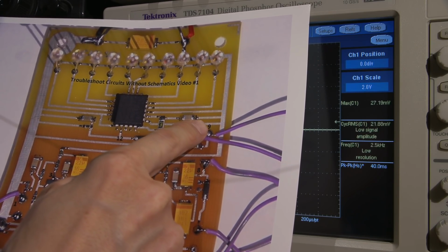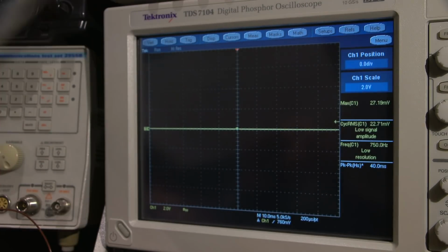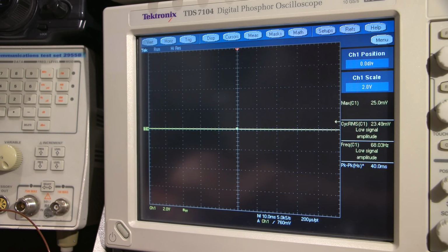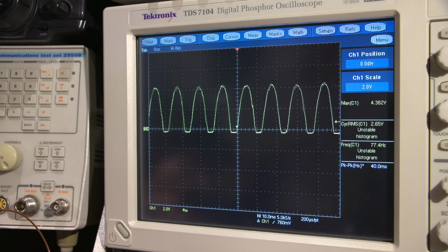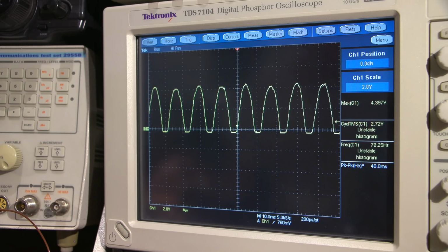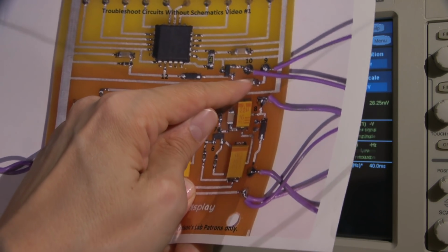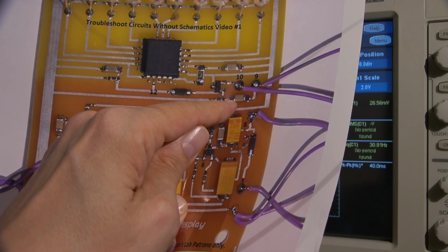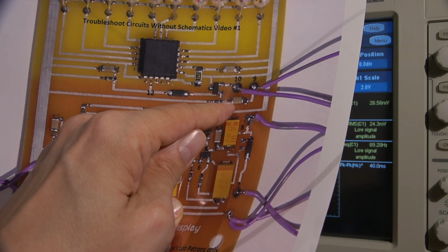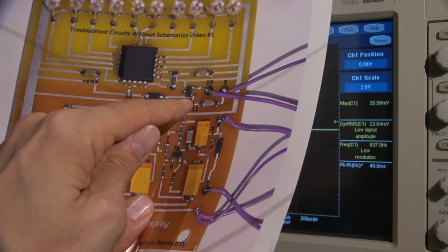Now, we see the signal at number 9 here when this is in the intensify position. So what I'll do is I'll click this back to intensify, and we'll go back to number 9 here. Get this back on to number 9. Click this to intensify. So there we go. What happens if we move now to test point 11? What are we going to get back at test point 11 right here? Technically, we're going to get what looks to be like a standard AC signal again. It should be at the center of the screen. So we'll go from 9 to 11.